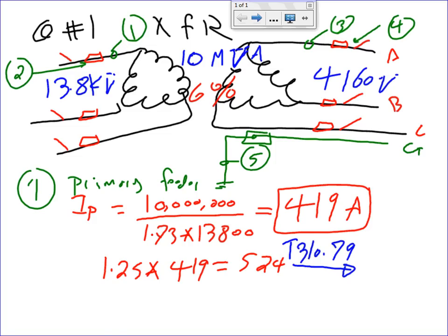So 90 degree Celsius. And I know I need 3 of them. Everybody knows why 3? What happened to the neutral, Chad? I don't need a neutral. There is no neutral, they're delta. 3 conductors, number 750. Thank you. Did you look at 13.8? You'll have to go to the other side of the table because there are 2 sides, because of the voltages.